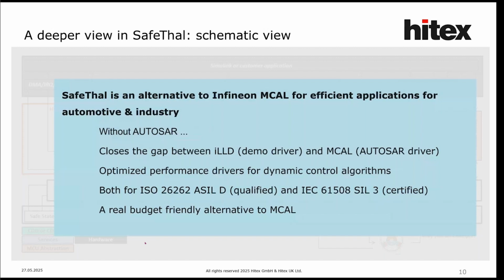With this, safety HAL is an alternative to Infineon MCAL for efficient applications for automotive and industry. When you don't use AUTOSAR, it closes the gap between the ASIL-D demo drivers from Infineon and the MCAL, the auto drivers for the AURIX. We offer optimized, performance drivers for dynamic control algorithms for ISO 26262 up to ASIL-D and IEC 61508 up to SIL-3. And it's a really budget-friendly alternative to the MCALs.